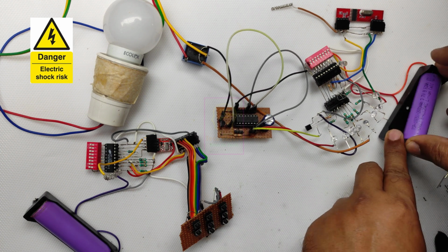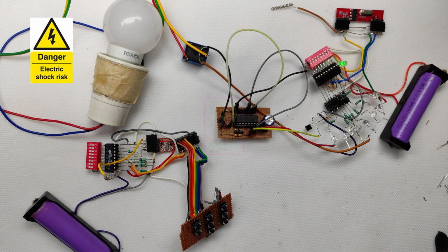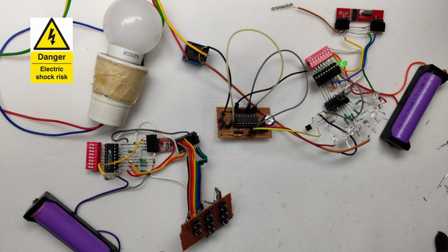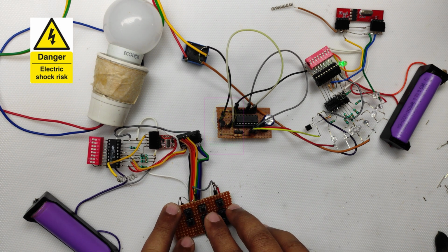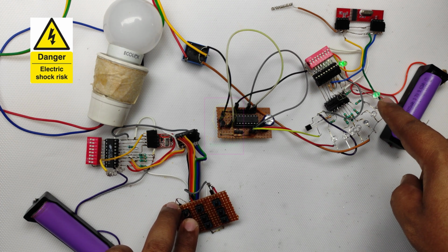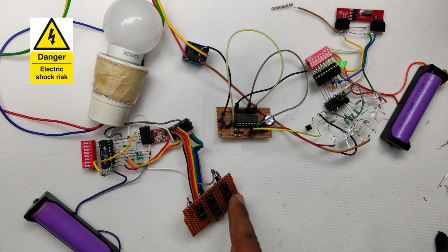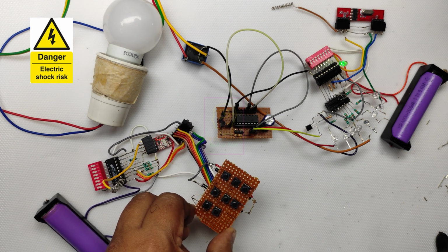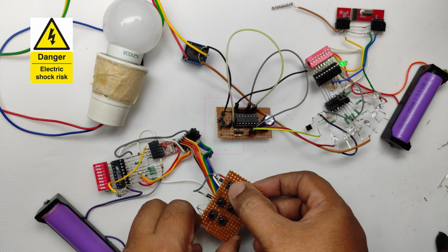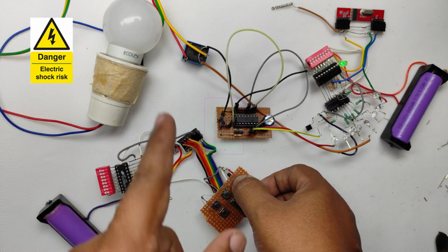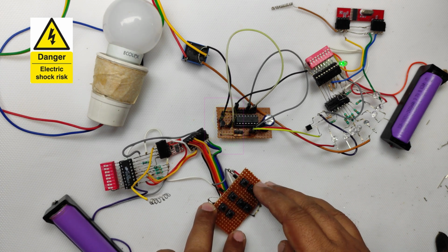Now testing time. We have attached only one device to it, that is a 1 watt LED bulb which is working on 230 volts. So when I press all other switches, you can see LED indication, and in one switch you can see the relay is switching on and off. The relay is connected with the 230 volts, so be careful. You can see the LED bulb is working perfectly fine. Once again I am telling, do not touch the relay terminals.